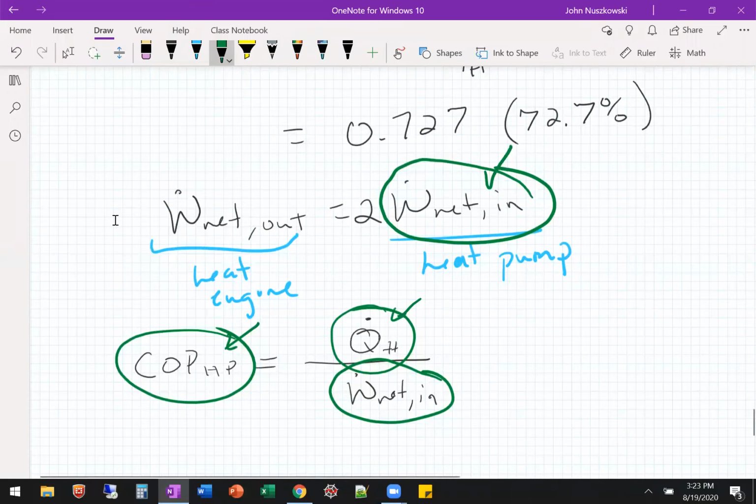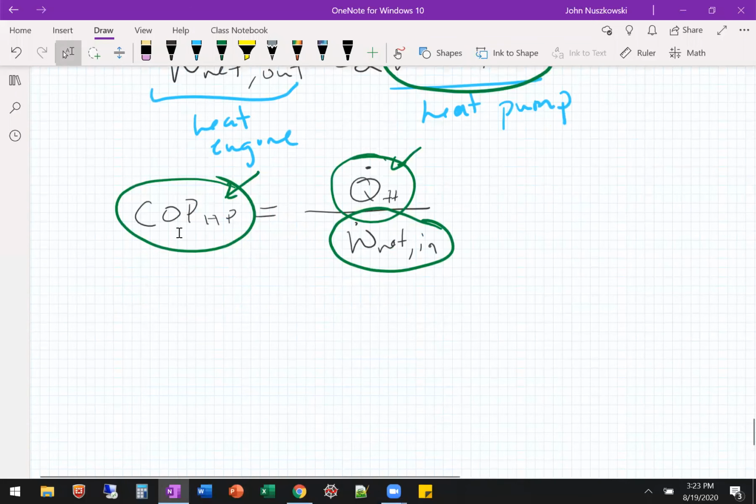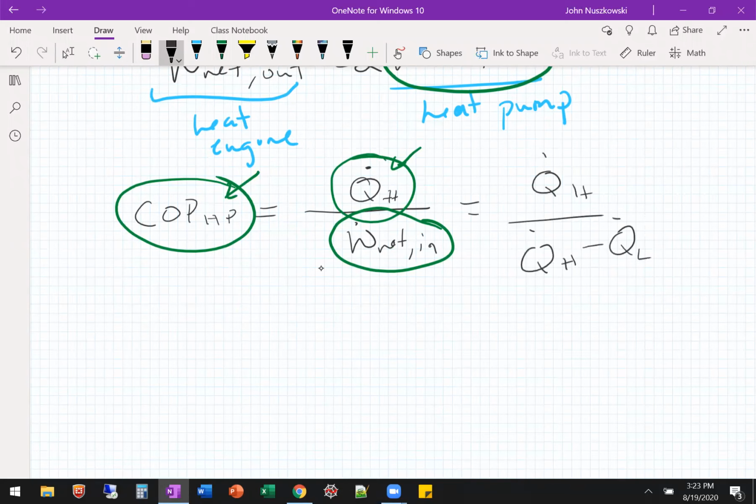All right, so we said, I heard the temperatures, right? So we can do the same kind of thing we did and use a reversible because it said it's Carnot already, right? So we can derive it again if we want. And divide by one of the Q's, QL or QH, and then the ratio of heat transfers is equal to the ratio of temperatures.